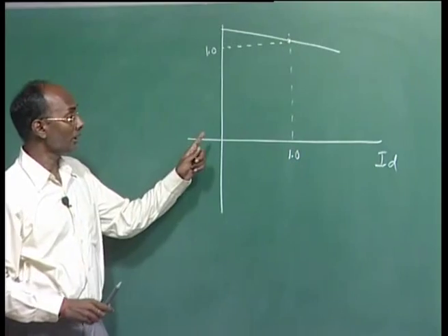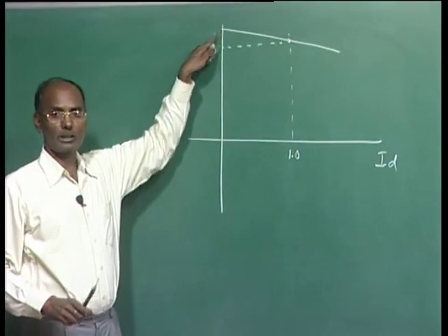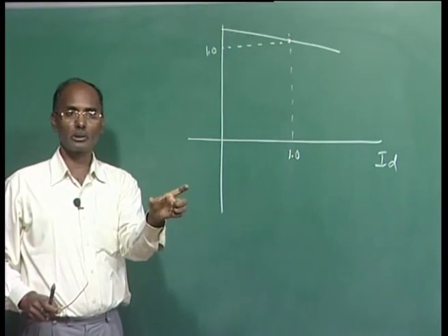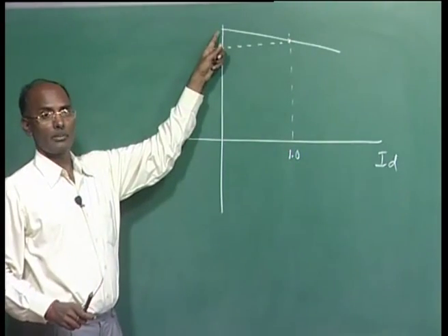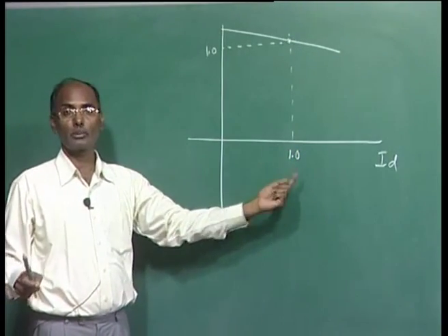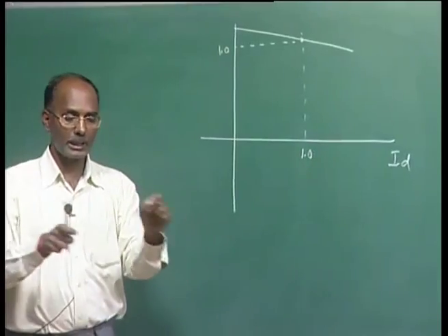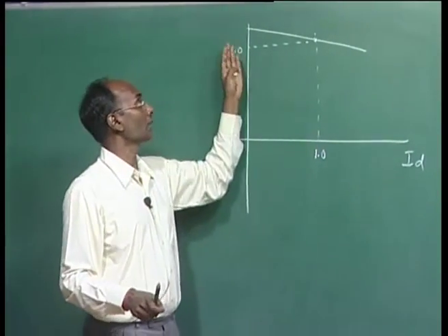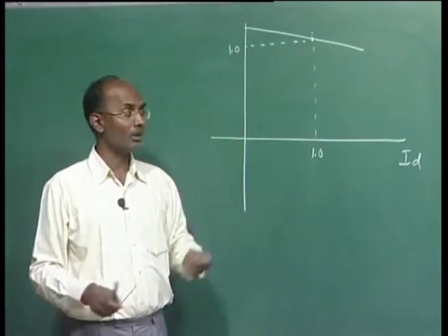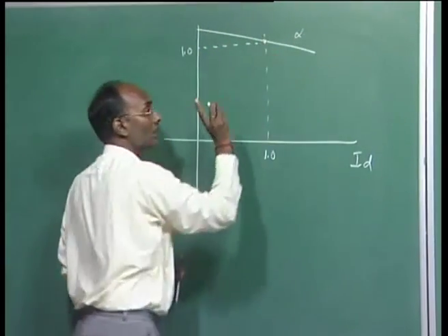Now you can say if this current is 0, your voltage is higher. We can just adjust the tappings and transformer turns ratio in such a way that we can maintain it here. Because we want our rated voltage to be 1 per unit and the current to be 1 per unit in the DC link, so that we can have 1 per unit power. Now whether we are decreasing or increasing beyond this, it depends on the voltage rather than current. So this side we are having your alpha control, and here